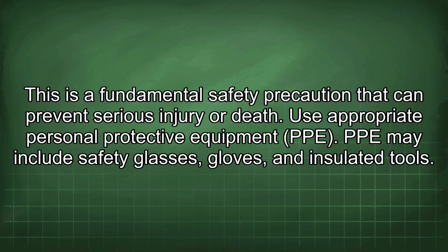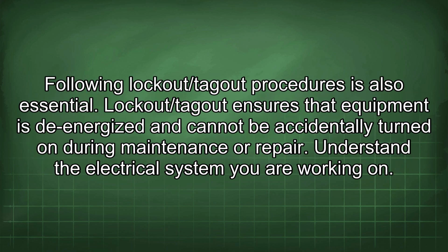Use appropriate personal protective equipment (PPE). PPE may include safety glasses, gloves, and insulated tools. Following lockout/tagout procedures is also essential. Lockout/tagout ensures that equipment is not energized and cannot be accidentally turned on during maintenance or repair.